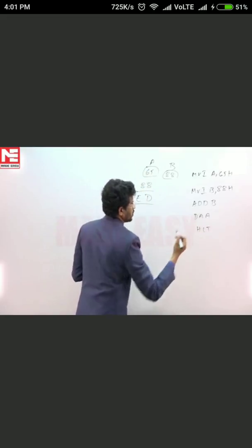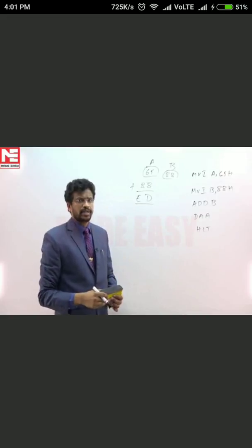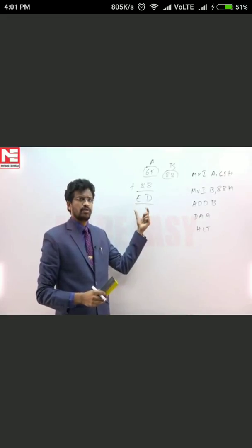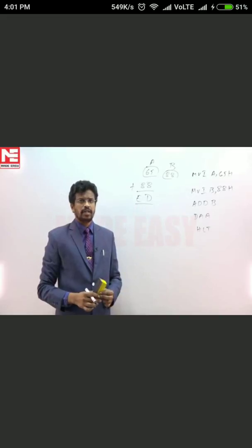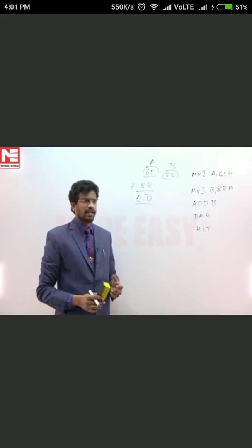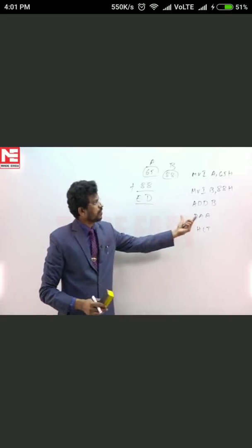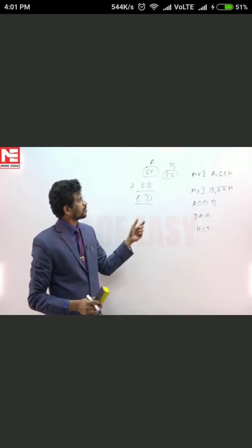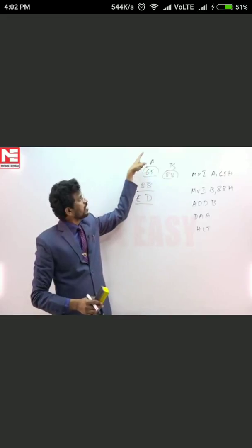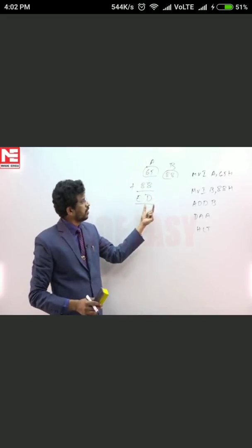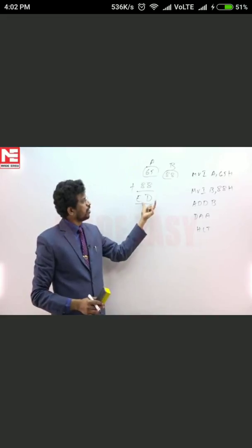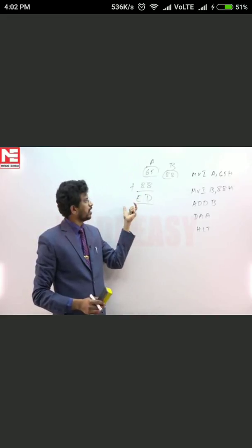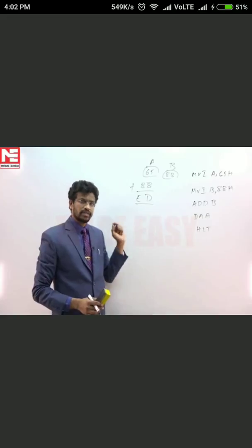And after that, DAA stands for decimal adjust accumulator. Accumulator value is adjusted to the decimal value. So the difference between decimal number system and hexadecimal is 6, therefore 16 minus 10 is 6, and hence there are two conditions for DAA. While adding, if the auxiliary carry is 1, then the lower nibble is added with 6, or if the lower nibble is greater than 9 or higher nibble is greater than 9, then also 6 is added.